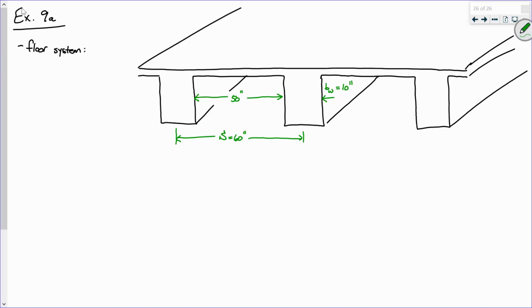Now, imagine that this floor beam is going on forever. So the idea is we're going to isolate a particular beam. So what I'm doing is this. So I have isolated a particular beam right here. So if you want, I can sort of carry this out like that. So really what I'm trying to do is say, all right, this little T shape that's in a particular range of the floor system, that is the T-beam that I want to analyze.